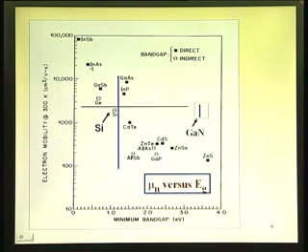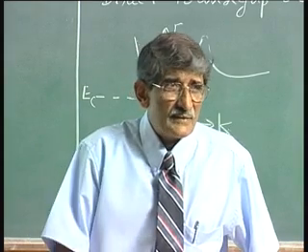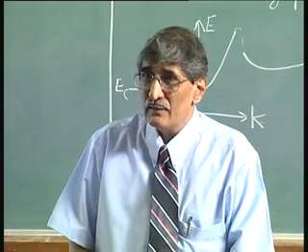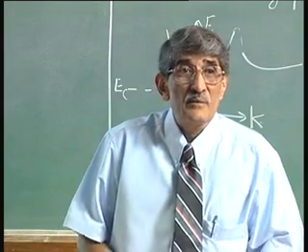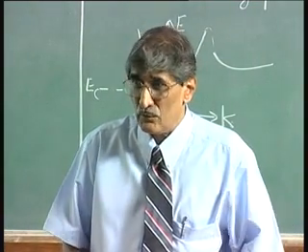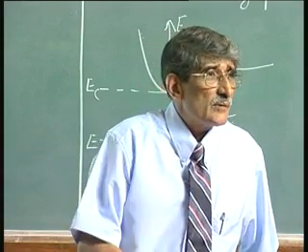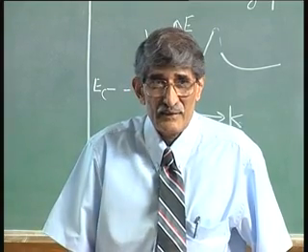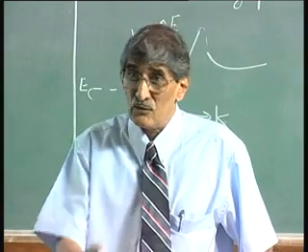It is very difficult to make a junction which works at room temperature, because lot of carriers are present, leakage current is large. Okay. Supposing your intrinsic carrier concentration is 10 to the power 18, how will you make it extrinsic? Make a p-n junction at room temperature. See, silicon intrinsic carrier concentration is 1.5 into 10 to the power 10 per centimeter cube, electrons and holes. Now, if you put dopants like 10 to the power 12 donors, that becomes n-type. It is very easy to make n-type material, 10 to the power 12, 13, 14, 15 at room temperature.